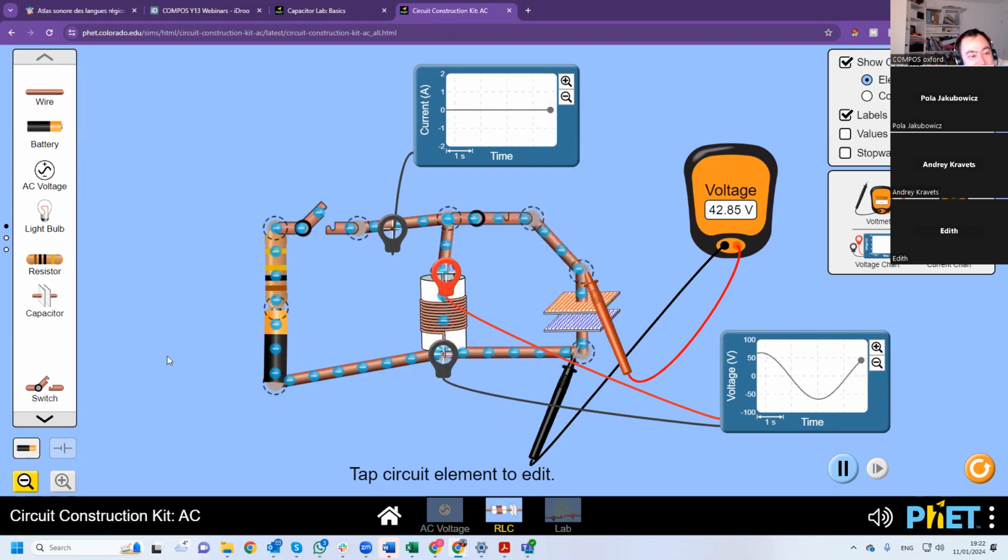So what's going on here? Well, because the battery is connected to the capacitor, to the inductor, there's a large current passing through the inductor. So the inductor stores a lot of energy. And when you disconnect the battery, all this energy suddenly goes into the capacitor. So it manages to charge the capacitor to 60 volts using a 9-volt battery.